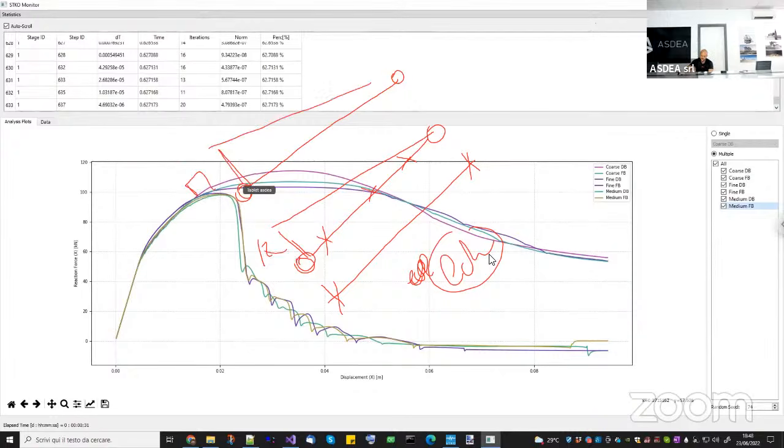Okay, so the bending moment is linear in this case. The curvature will be different. To have the same bending moment, but this point here, for example, is fracturing while this one is not, you will see a very high deformation here and a smaller deformation at the other points. So the deformation is not imposed to be linear, it's not imposed to be continuous, but it can be discontinuous between the different Gauss points.